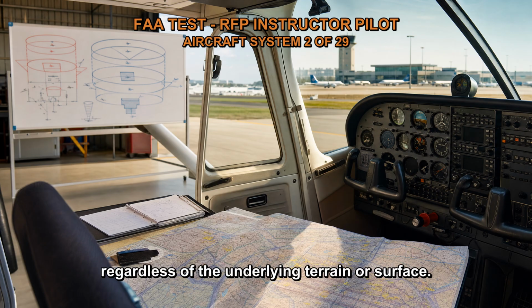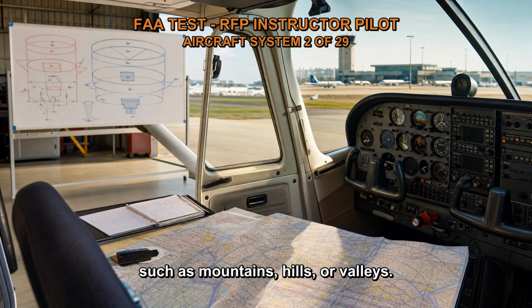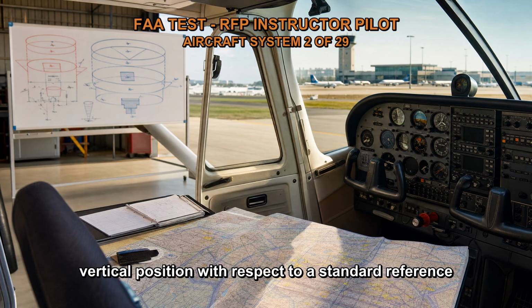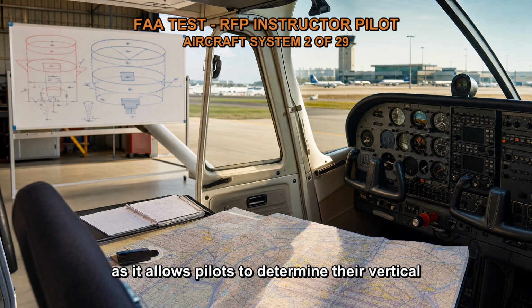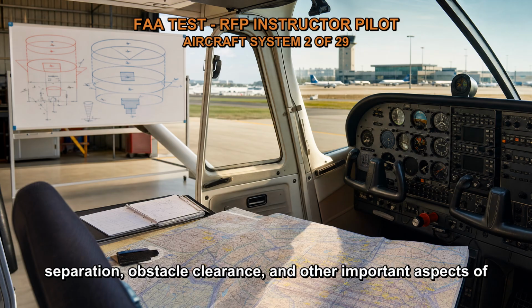regardless of the underlying terrain or surface. This means that true altitude takes into account changes in elevation caused by variations in terrain, such as mountains, hills, or valleys. It provides an absolute measure of an aircraft's vertical position with respect to a standard reference point, which is mean sea level. True altitude is an essential measurement in aviation as it allows pilots to determine their vertical position in relation to the Earth's surface. It serves as a reference for navigation, airspace separation, obstacle clearance, and other important aspects of flight.